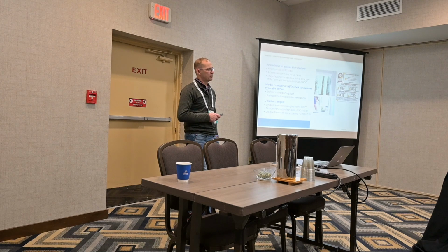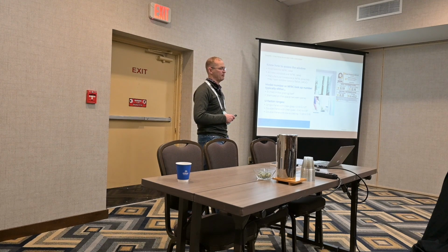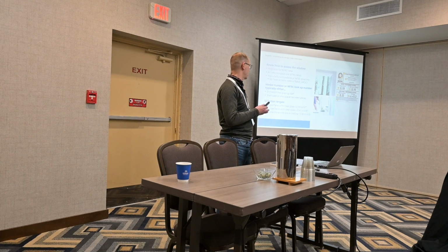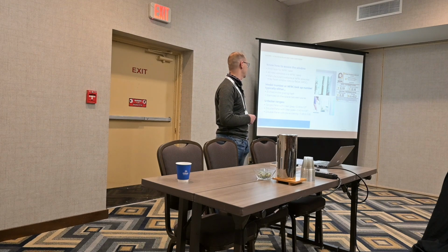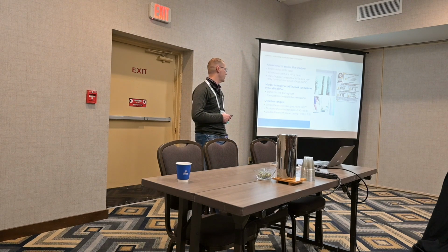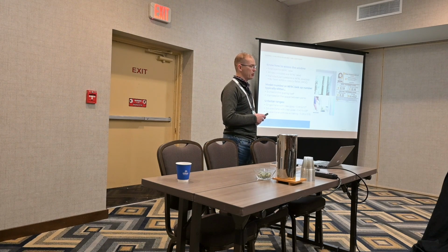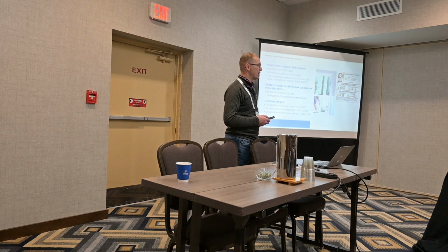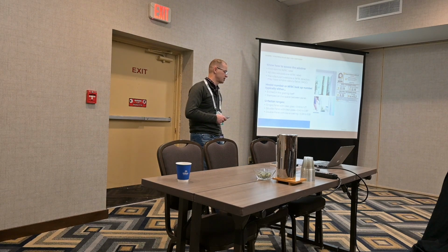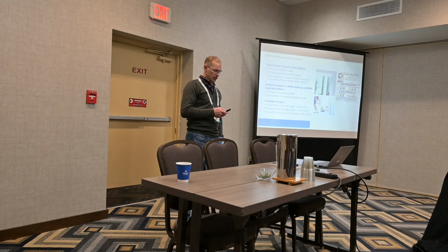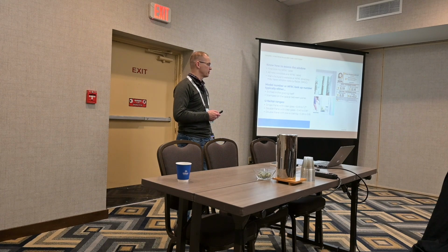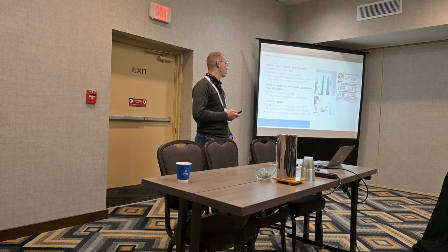Double panes, per building codes that have been updated to be more strict, but traditionally in the past, 0.40 was a decent number. Double pane windows with low-E coating can get even lower, and nowadays they can get as low as 0.2. So it is important to make sure you have those numbers, since those will impact your heating load.